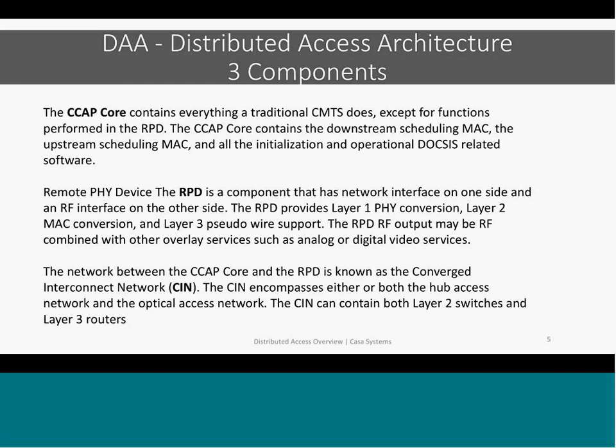So the RPD has to have a layer 1 connection, connecting it to the core, and then a connection to the plant. So the RPD really takes packets in, IP connections in, and up converts to the QAM of the service that you're deploying. Could it be a single carrier QAM for high-speed data, or a QAM for video, a broadcast or a narrowcast QAM, whatever it may be. That RPD takes the IP physical connection in and does RF out.